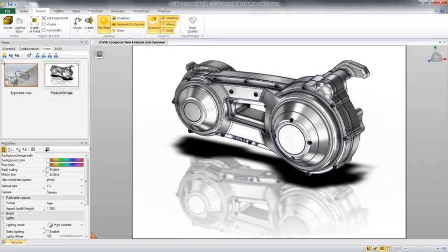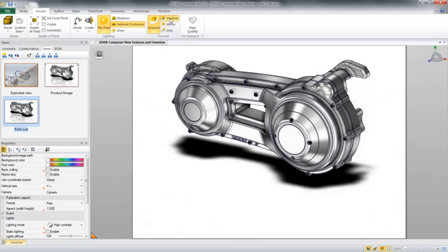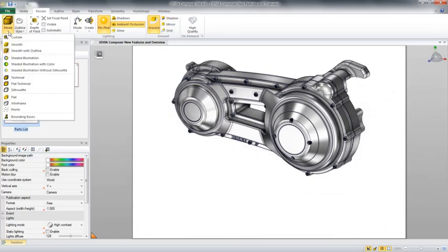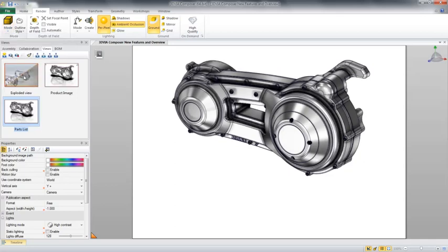In this example, we're going to create a simple parts list to show some of the new capabilities as well as review what 3DVIA Composer allows us to do. To start, we'll want to take a look at a few of the graphical settings, including the environment. We can turn off things such as the grid on the floor, the mirrored surface, and shadows. We can also change the rendering characteristics of the model itself.